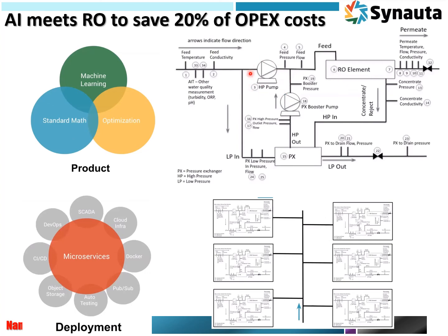So you have a very high pressure pump, push it through your RO element, and after this element your water is desalinated, and then goes to the RO brine. The pressure exchanger will be applied, and then it goes to the boost pump, which is also called the balance pump, so that you have three pressure related units for your one RO module element.